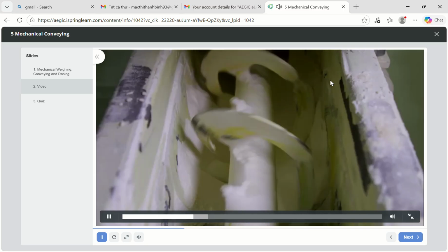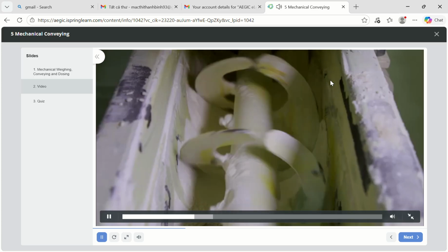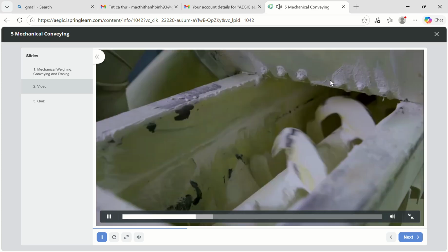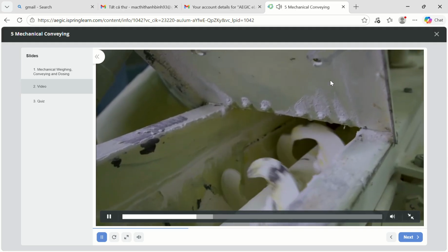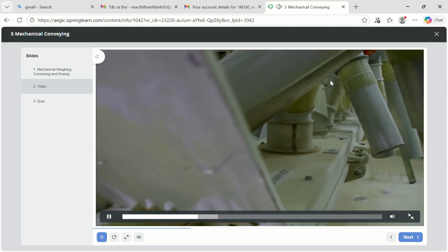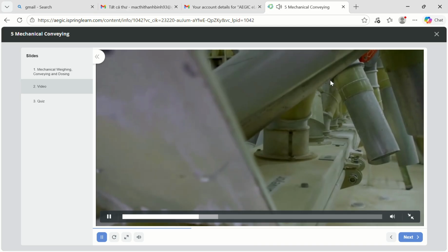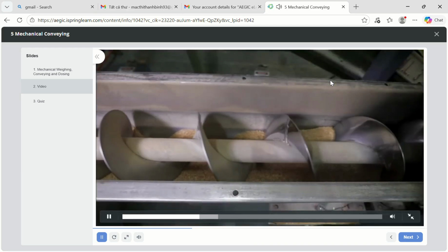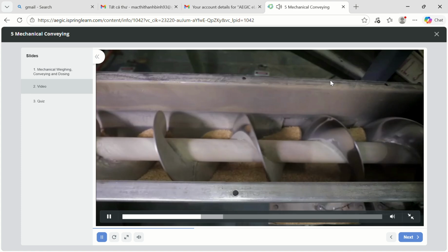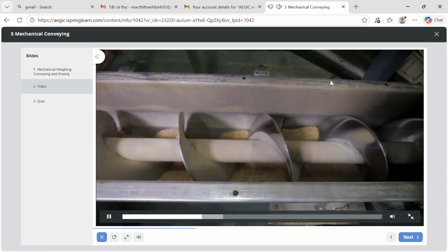Where the purpose is both conveying and mixing, a discontinuous screw may be used to increase the mixing action, such as in flour collection conveyors. As the screw spins, the product slides downhill against the ribbon of the screw, propelling the stock forward.